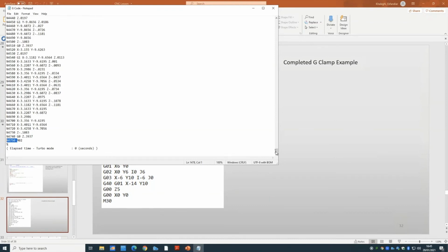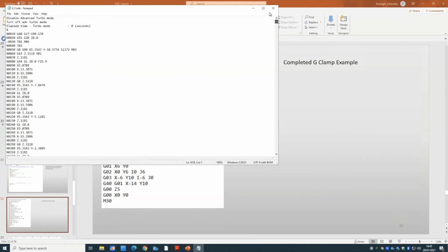For the part of the assignment, I recommend you pick a few lines of it. You can pick a specific section and then talk about it. Now you should be able to do it. You have the template of those G codes and can explain. Now it would be quite straightforward to go through them, where you set it, where you use it. You understand, for instance, making a zero as the G54, G43 tooling compensation, or G28 going back to home, which Eric mentioned after the lecture.